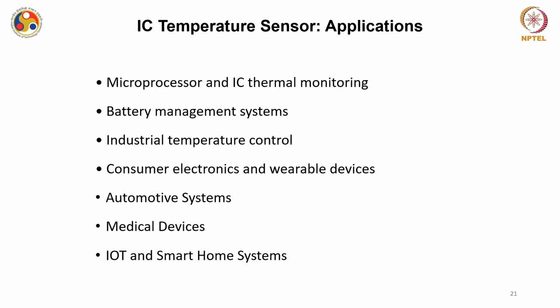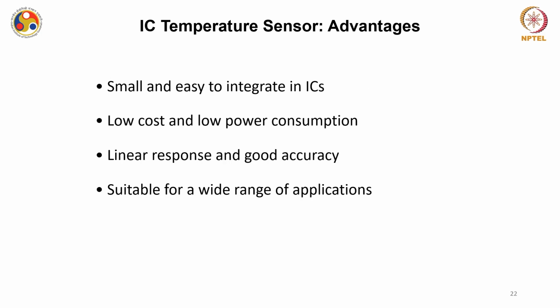found their application. Okay. In automotive systems, usually it finds its application only partially because it cannot go beyond 150 degrees Celsius, or the performance is mostly non-linear beyond 150 degrees Celsius. It is partially used in the automotive system, okay, but it is very popular in medical devices and IoT and smart home systems, okay, where the temperature is expected to not rise beyond 150 degrees Celsius, okay.